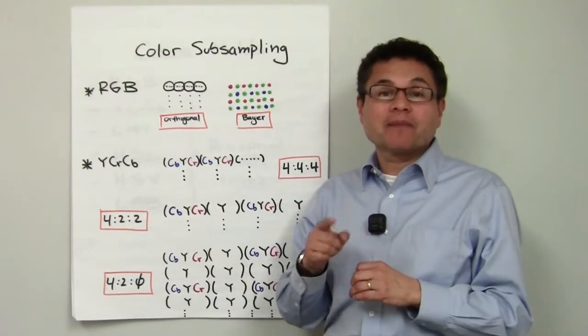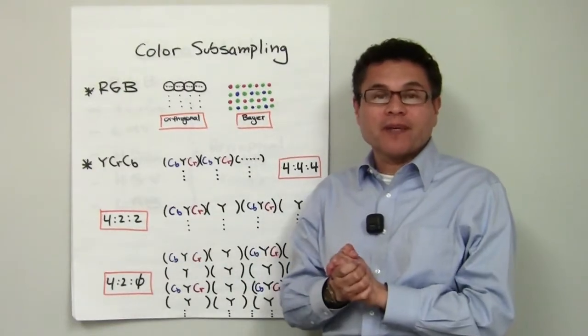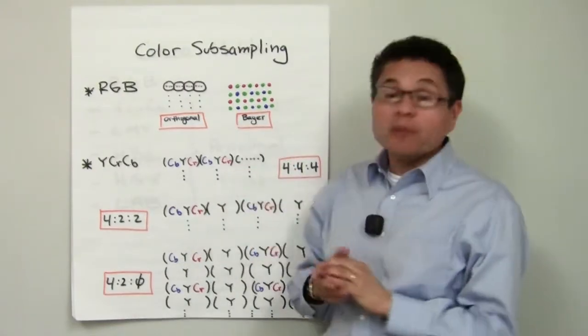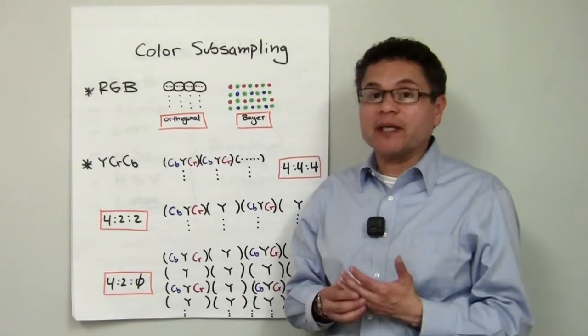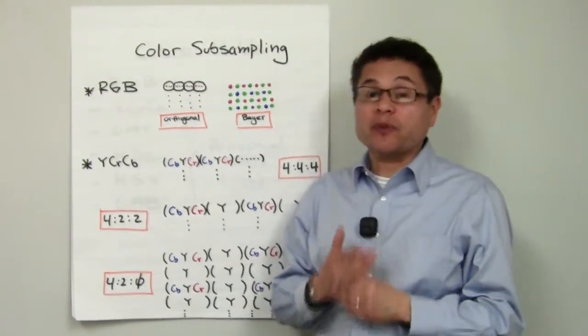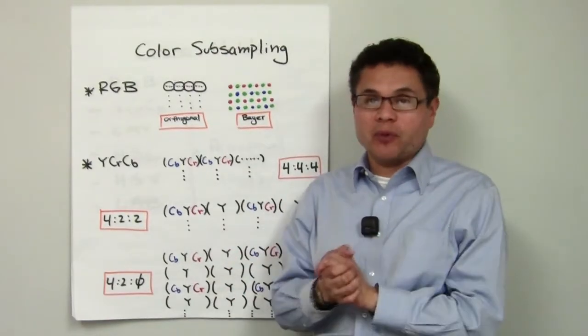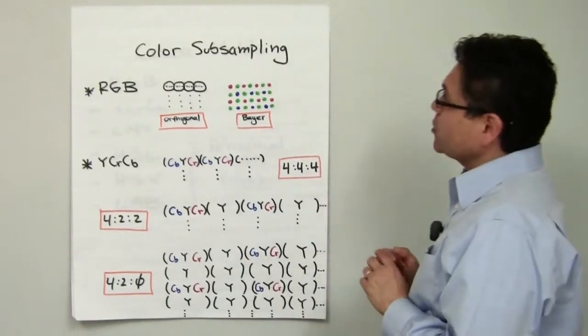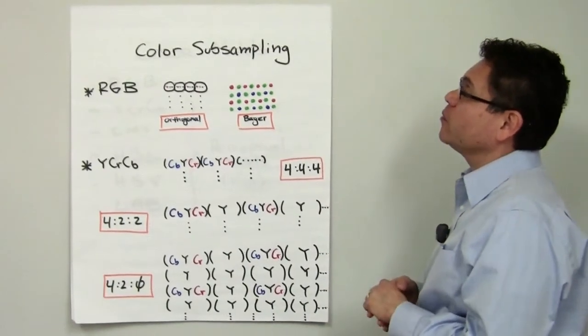And there's even a little bit of the red spectrum that spills into the blue. Because of the response of the human eye, we could do color subsampling. In other words, we could use fewer samples to represent color than we use to represent luminance, the Y component. This graph shows that there are many subsampling alternatives that you may approach.